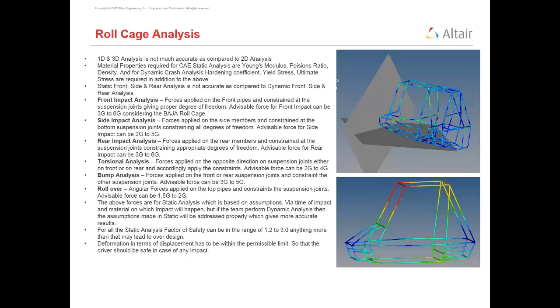For all static analysis, the factor of safety can be in a range of 1.2 to 3. Anything more than that may lead to over-design.